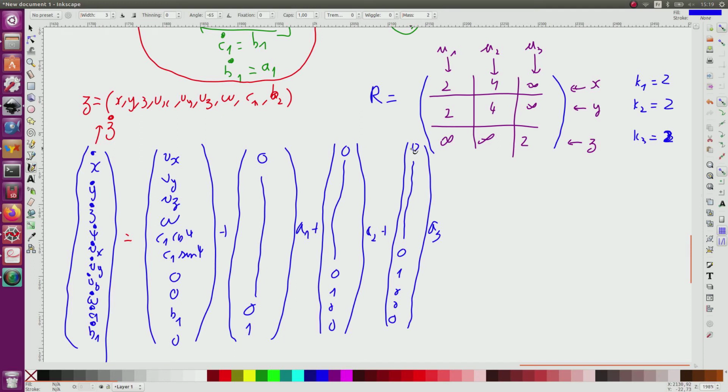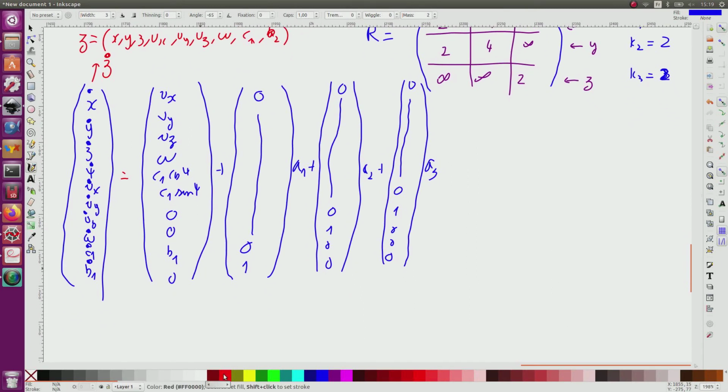Okay, so it is important to write like this if I want to use Lie derivatives with symbolic calculus. So this one corresponds to what I call f z of z. This one is g1. It should depend also on z, so g1, g2 and g3, but in this particular situation they do not depend on z. And here are the inputs. Normally fz, g1, g2, g3 correspond to vector fields, since they correspond to an application which to z associates a vector which has exactly the same dimension as z. So b1 and c1 correspond to the state variables attached to our two integrators.